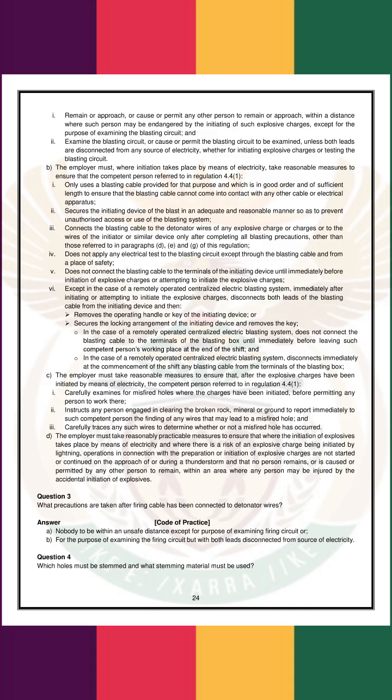The employer must take reasonable measures to ensure that, after the explosive charges have been initiated by means of electricity, the competent person referred to in Regulation 4.4.1. Carefully examines for misfired holes where the charges have been initiated before permitting any person to work there. 2. Instructs any person engaged in clearing the broken rock, mineral, or ground to report immediately to such competent person the finding of any wires that may lead to a misfired hole. 3. Carefully traces any such wires to determine whether or not a misfired hole has occurred.